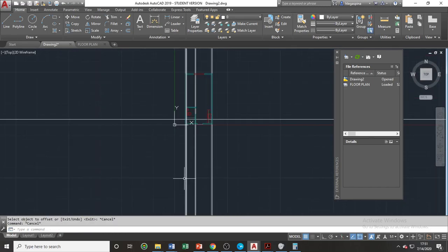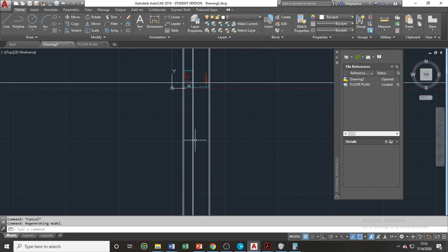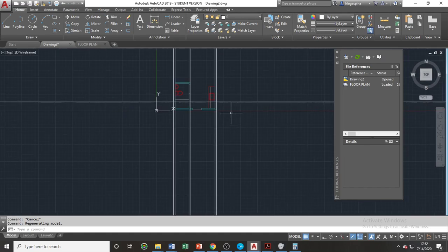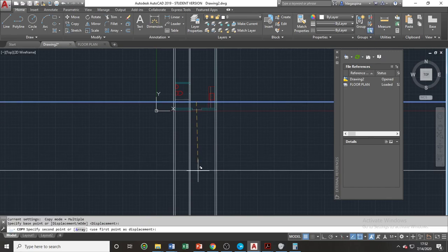Once our construction line is set, we will now create projection lines for our floor finish level and our ceiling level. You may also include the thickness of your slab if you prefer, and the slab at the top as well.